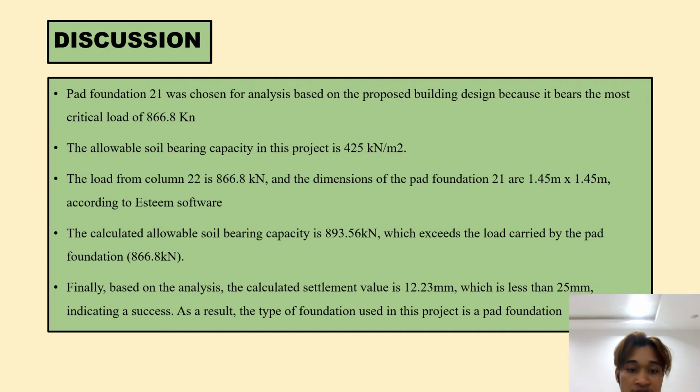Finally, based on the analysis, the calculated settlement value is 12.23 mm, which is less than 25 mm, indicating a success. As a result, the type of foundation used in this project is a pad foundation.